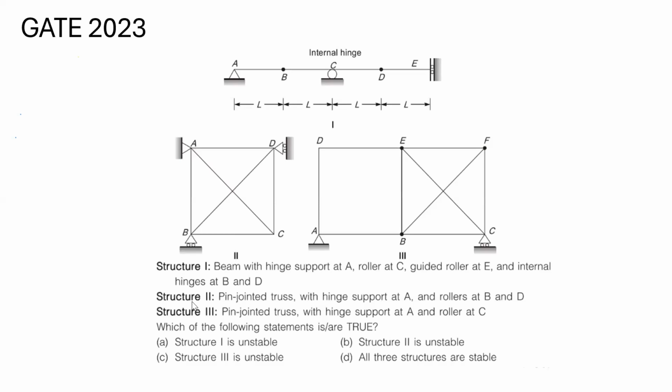So we will calculate the DS, and based on the DS, negative or positive, you can comment whether the structure is stable or unstable. See the next, the second structure. It's a square truss structure. D and B, both are rollers. But here, I want to say that you should not rely only on the equations. See the physics in the structure. The equation may give the wrong results.